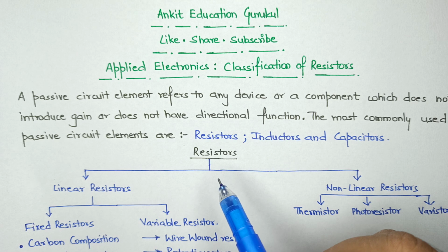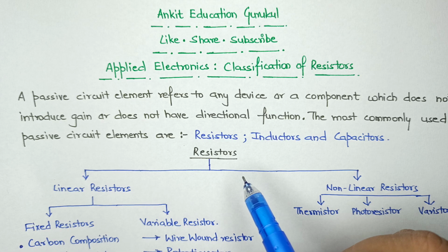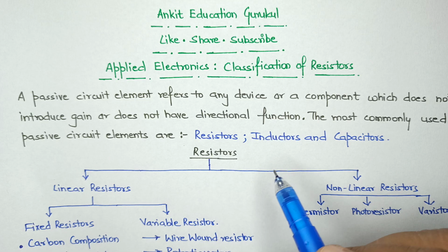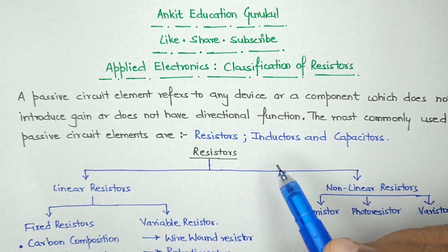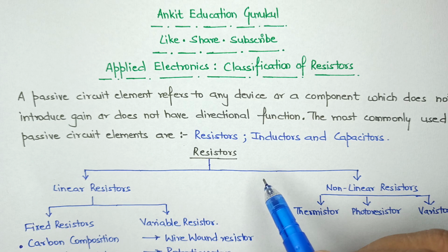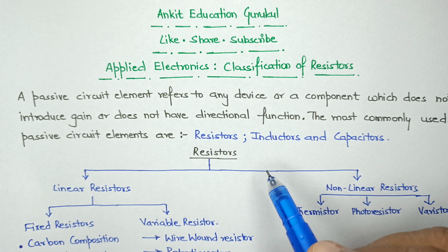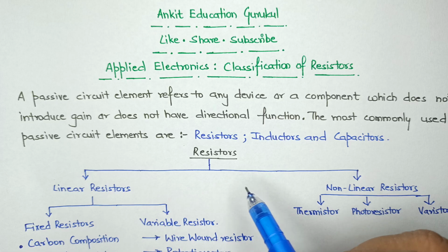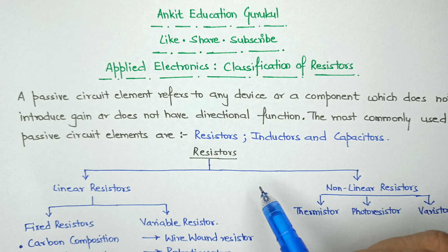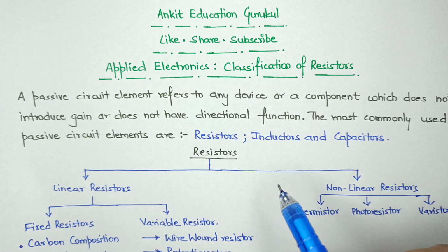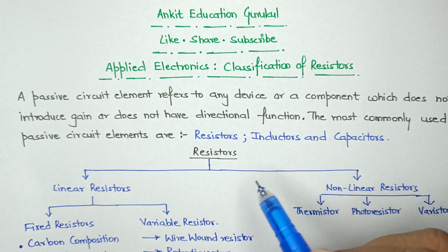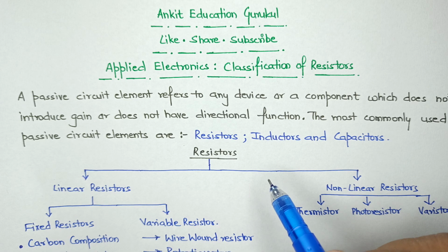Usually, carbon composition resistors will fail if operated at or near the rated power values. In this case, the resistor will not burn out, but the failure is gradual, which may take many months. It changes gradually to a much lower resistance. This causes improper operation of an electronic circuit, particularly an amplifier. Thus, in order to increase the life of the resistors, they must be used at much less power than their rated values. A standard practice is to use a power dissipation of about half of the rating of the resistor.